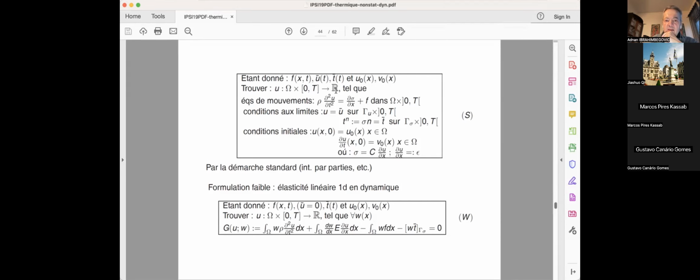And so then I can solve this so-called initial-boundary problem. Initial because you're talking about imposing initial displacements for t equals 0. And boundary because we're talking about imposing the boundary displacements or tractions for a particular value of x that is sitting on the boundary.